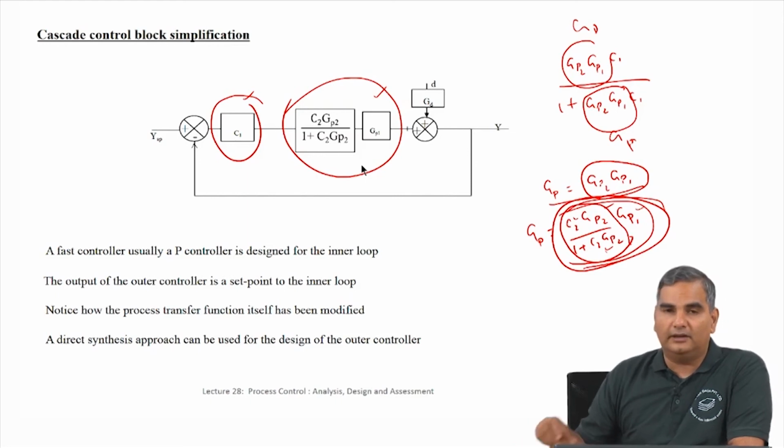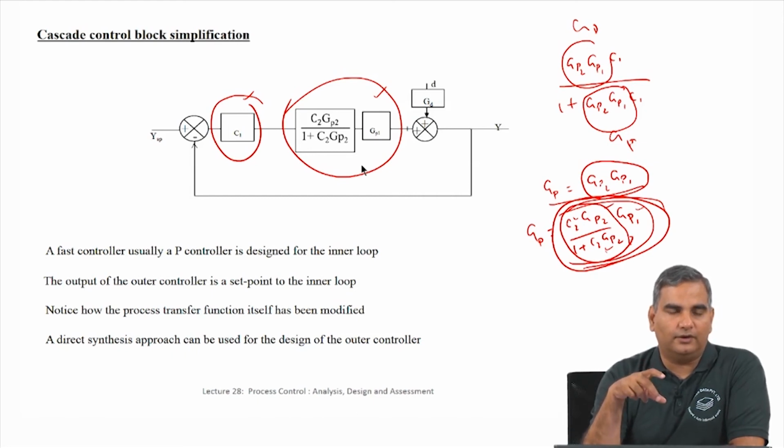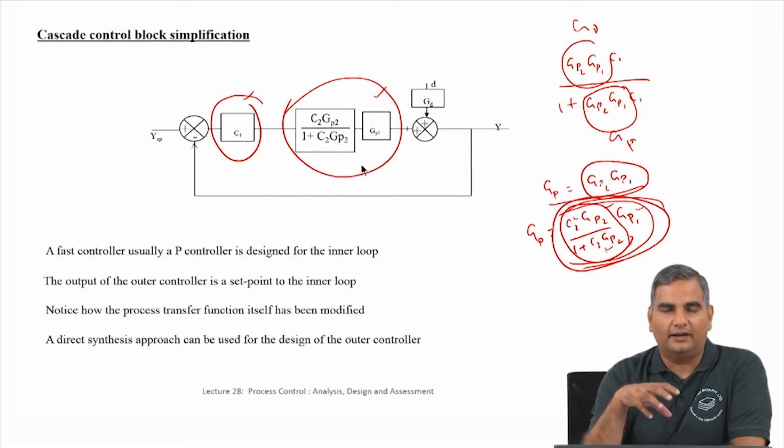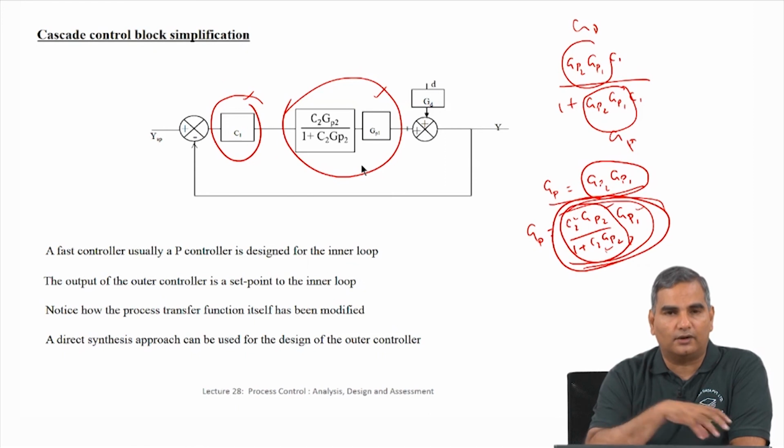What this would do in terms of physical system is, if the inside dynamics, the valve dynamics is a particular rate without closing the inside loop, by closing the inside loop, what we are doing is we are making the valve dynamics faster, right, because the typical idea of a controller is to make sure that your closed loop dynamics is faster than your open loop dynamics. If I did not do a measurement of the stem position and then close the loop, I have to live with the normal valve dynamics, but because I do a measurement of the stem and close the loop, I can now have valve dynamics which is faster than normal, which will help with the overall control of the system.